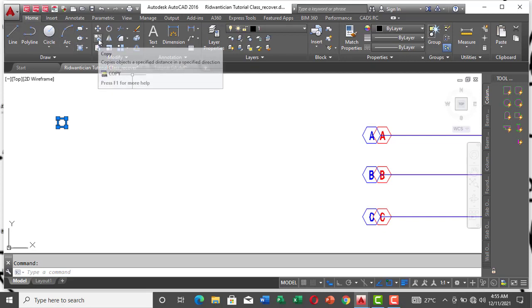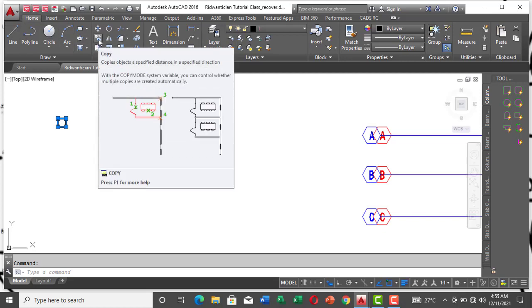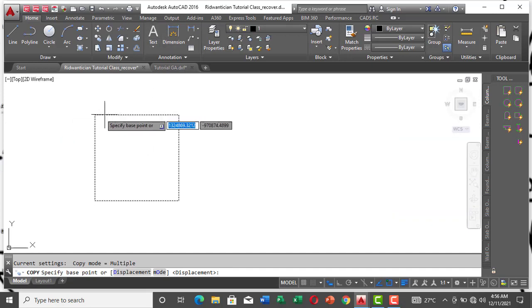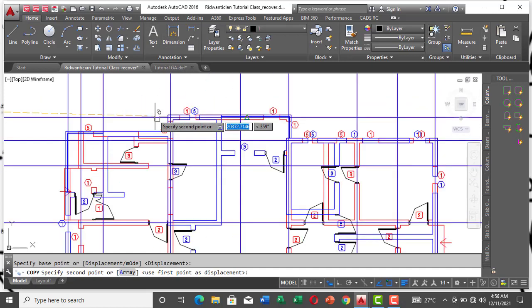As I've said, where it is needed is the four corners of the building, where you have a cantilever, and where you have a staircase. Yes, and at the beginning of the staircase you should put a column, and then some other important places. So pick a base point. Let me pick here. Now let's see, we can drop it.